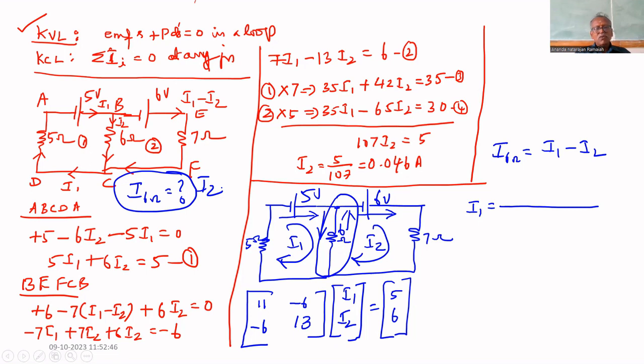So I6 ohm equal to I2 in the first part. Why? We are assuming that current through 6 ohm equal to I2. In the second case, as rightly mentioned by some students, current through 6 ohm is I1 minus I2. Why? Because both currents, I1 as well as I2, are going through that path of 6 ohm. Therefore, current through 6 ohm equal to I1 minus I2.